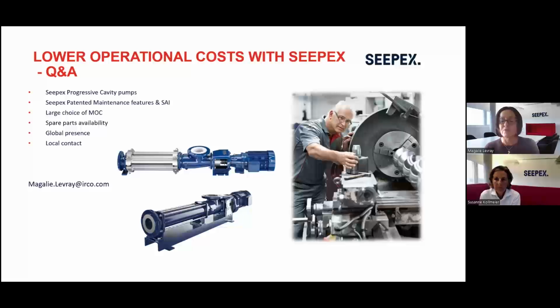Today, I would say that progressive cavity pumps, especially with all the design features we have on the T series, we are able to transfer very thick slurries with high density, close to above 3. So today, I would say that we have higher flow rate and higher pressure capabilities. That makes the difference, and that's why it opens wider applications for PCPs.